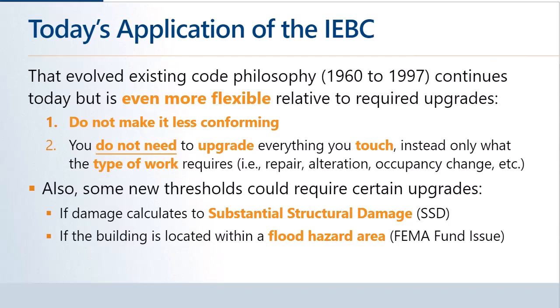Same thing with a flood hazard. If your building is in a flood hazard area, there are specific terms defined in the code. There's substantial damage, substantial improvement. Okay, they are different and distinct from SSD, but nonetheless, you should be aware of them. The important thing is, if you trigger one of those, it doesn't cause the project to not be a repair project anymore. It just may lead to additional work that you were not otherwise anticipating.